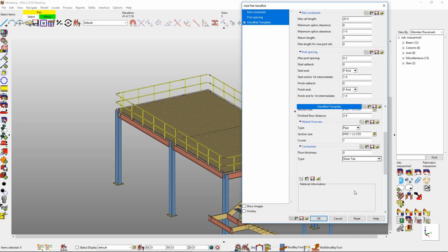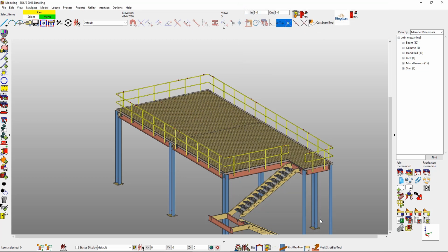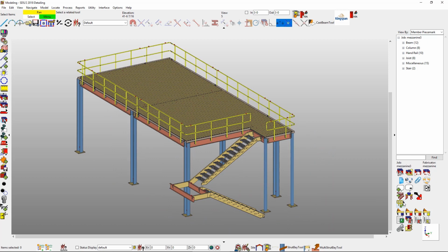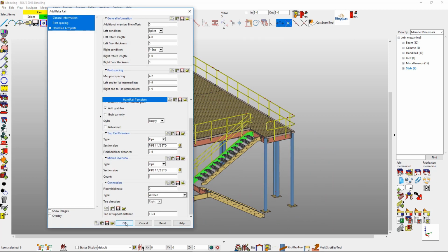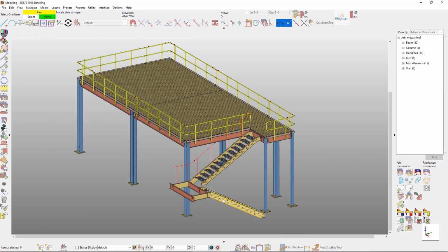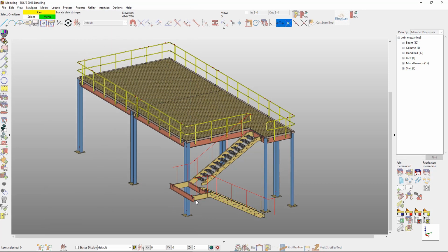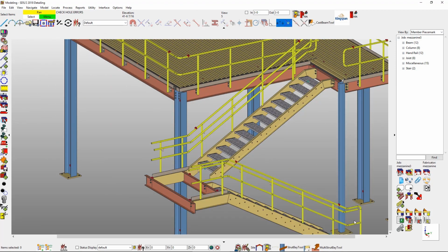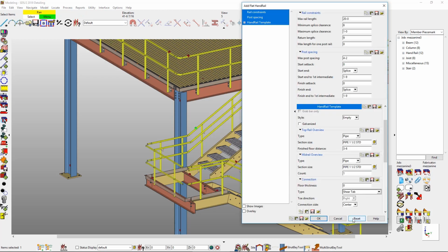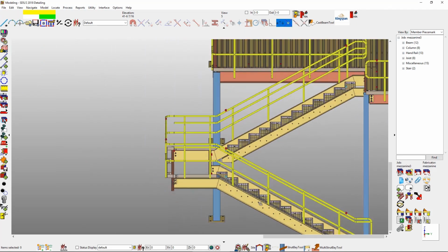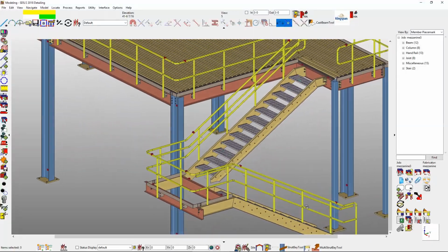As you can see, this is making it a very quick input. Once you're given the location of the handrail, then you can load in the company standards already created, or you can update the fields necessary for that situation. Features in SDS2 will automatically calculate any returns when simply picking a stair stringer. Using handrail tools such as connecting the rail at the landing, changing splices, or moving posts can all be done on the fly. Enhancements done to the stairs and rails have made them just as easy to add as primary members and just as profitable to detail.